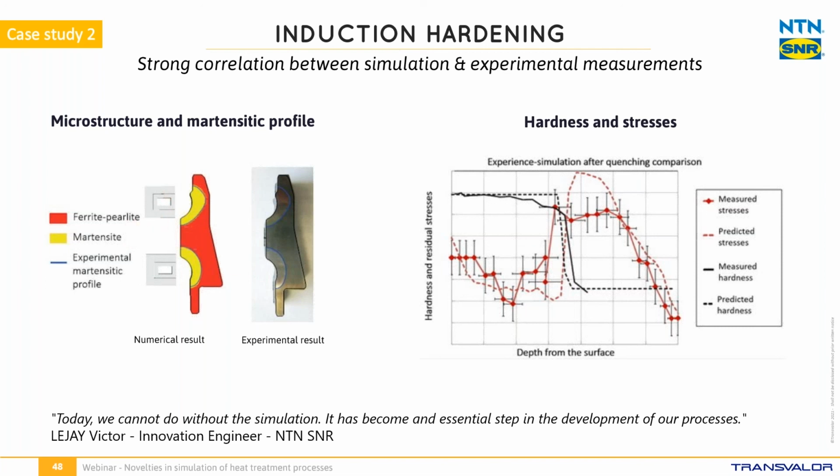To the right, we have the hardness and the residual stresses as a function of the depth from the surface. In dot dash are the numerical results. The residual stress curves are plotted in red and the hardness in black. Numerical hardness values are in very good agreement with the experimental ones.